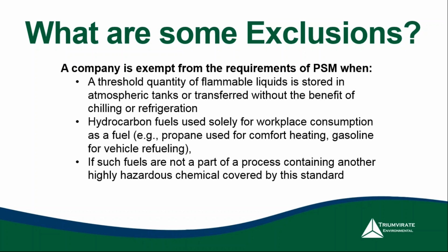Again, very similar to a lot of other rules, if it's there as a fuel, you might be able to get out of it. But if that fuel is part of a process that's covered by the standard, then you may not be included in it. That's why I'm saying you've got to really look at every single part of this before you can say, okay, I'm out or I'm in. You really want to rip apart that chemical inventory.